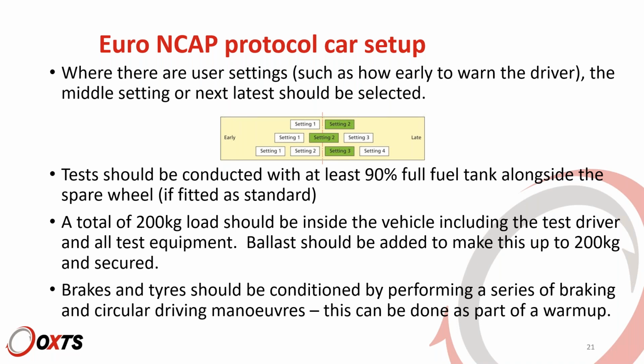So it's probably simplest to install the RT and configure it, ensure that the vehicle is at weight and configured in terms of the settings, and then the brake and tyre conditioning can be done as part of the warm-up, and both will be done together at the same time. So the RT warm-up doesn't have to be an extra step that takes longer, because you would have to do these maneuvers anyway to adhere to the protocol.